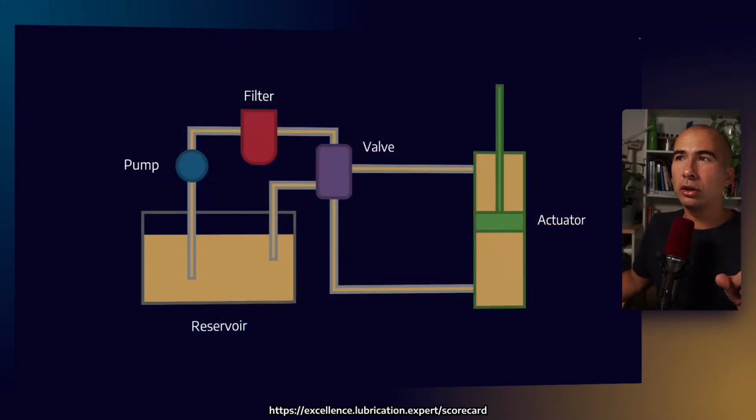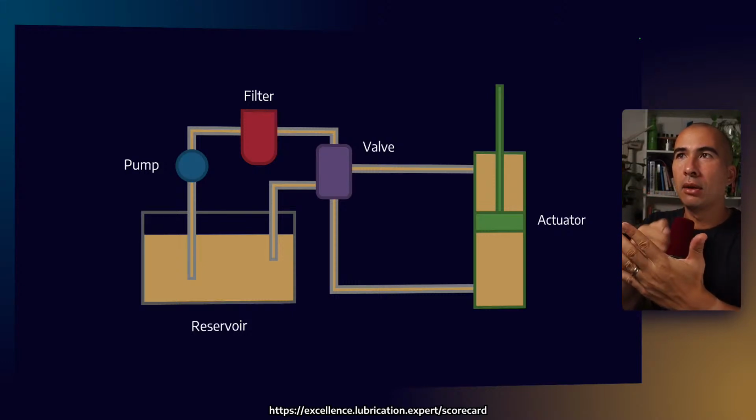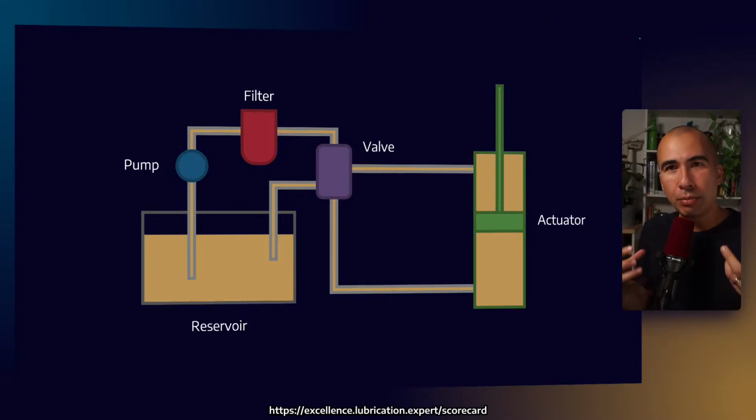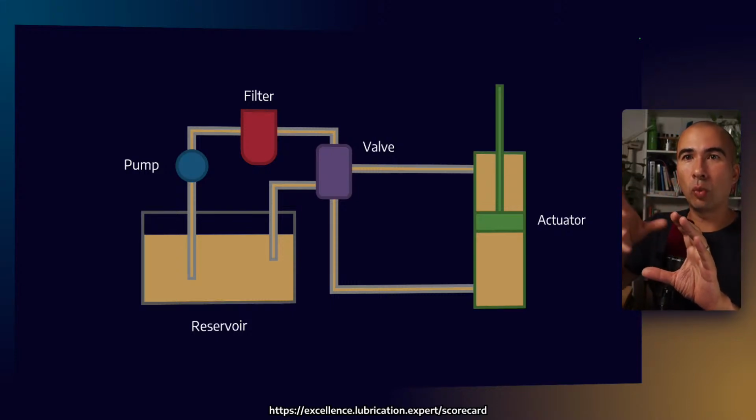Then we move on to the hydraulic oils. Now, this is a typical hydraulic circuit. Think about what a hydraulic oil has to do. Uniquely among all the lubricants, it needs to transfer power, right? That's the one big difference between the hydraulic oils and all of the other counterparts. But when we're talking about protection, what are we primarily protecting? We're primarily protecting the pump. The pump is where most of the wear occurs.